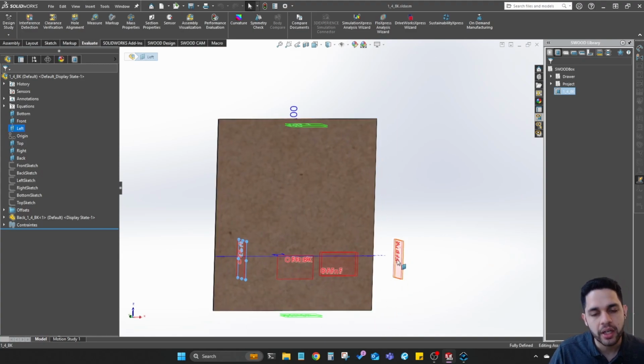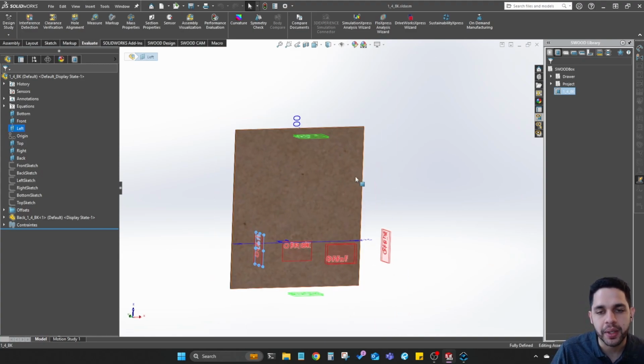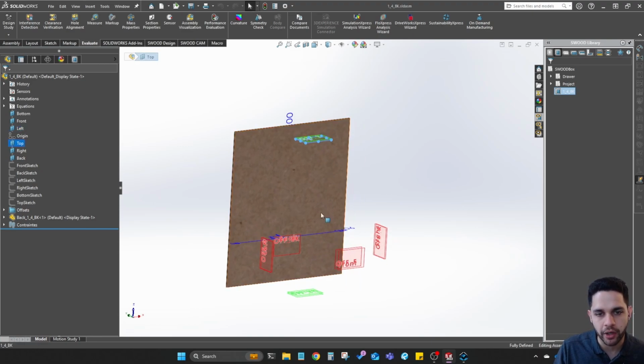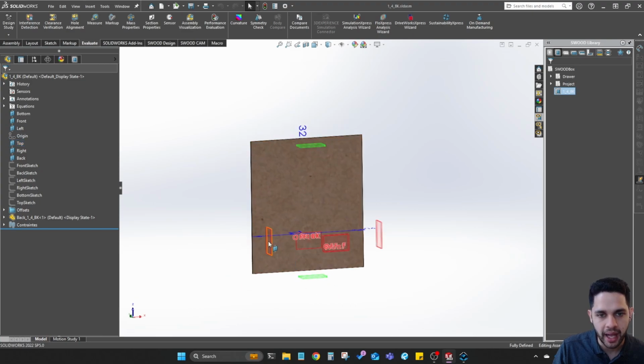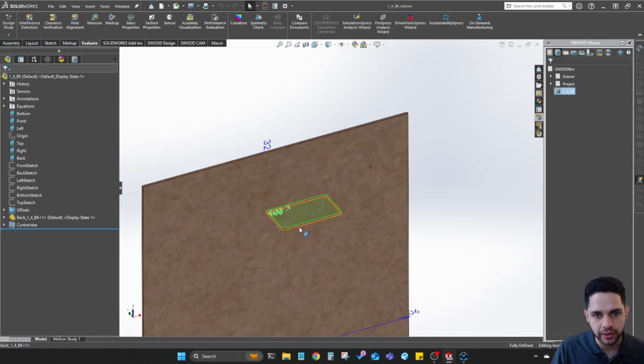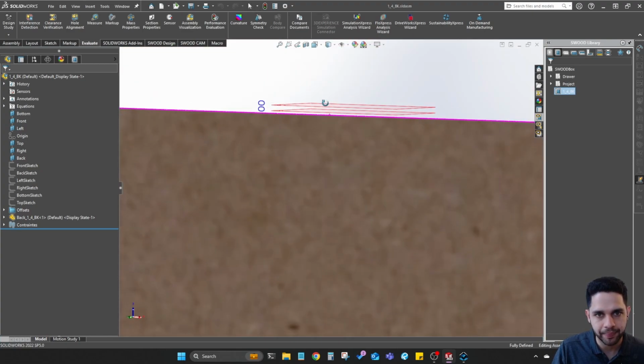And yes, we are going to be doing a dado on all 4 sides, but really, since we're going to be mirroring over our machinings, we only have to do that sketch on one of each of those sides. So the top will be mirrored and it'll be done. The machining will also be done on the bottom, and then we'll do a sketch on the left, and that machining will be mirrored over onto the right. So let's start off with a sketch on our top plane.